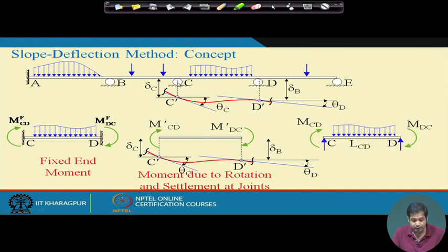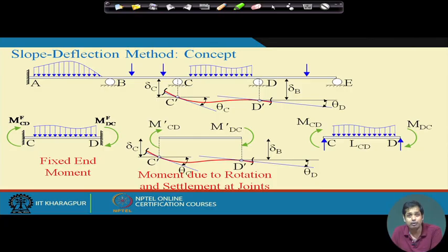So if we draw the free body diagram of member CD, there will be shear force and the moments. Recall that in the previous lecture, when we used free body diagrams, we always showed the moment in the direction whether it is sagging or hogging. We will still continue the same convention while drawing the bending moment diagram. Here the bending moments are shown in a clockwise direction, because in all the procedures to follow, we'll do many algebraic calculations, and it will help us to be consistent.